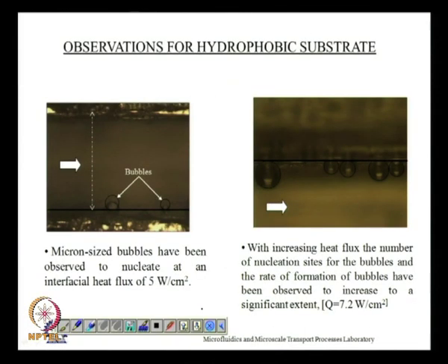There have been theoretical papers published which predict that a nanobubble covered layer would give lesser values of pressure drop. What was observed was that for higher roughness surfaces, if the surface roughness is quite large, then you would see that some of those protruded portions of the sidewall may go beyond the bubble covered layer and thereby increase the pressure drop. That is also to some extent obvious, but what would happen when you make a surface hydrophobic or make a surface hydrophilic? That is something which is going to be interesting.